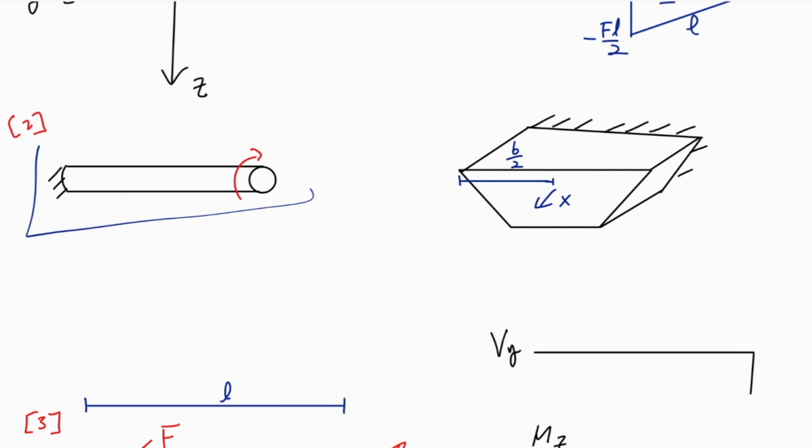So imagine this case right here. When we apply a rotational motion on one end, the clamped end has to oppose this because my bar has to be static. This opposing creates a torsional moment, which is the exact definition when 2 x direction moments counteract each other. Imagine if we had something like this, which again is a later chapter. If I had a force being applied in this corner, F, it would induce a rotation like this across B half. So this would induce a torsional moment of F times B half.